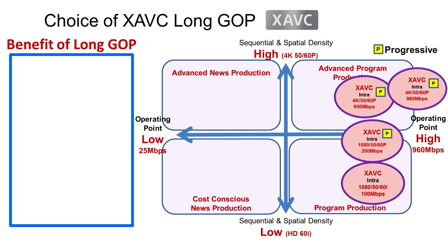And using intra-frame compression, we could do 1080 interlace, so 720 at 60p at 100 megabits per second. That is also intra-frame compression. We could do 60 progressive 1080 at 200 megabits per second. This is simply utilizing intra-picture compression, no inter-frame or multi-picture compression.